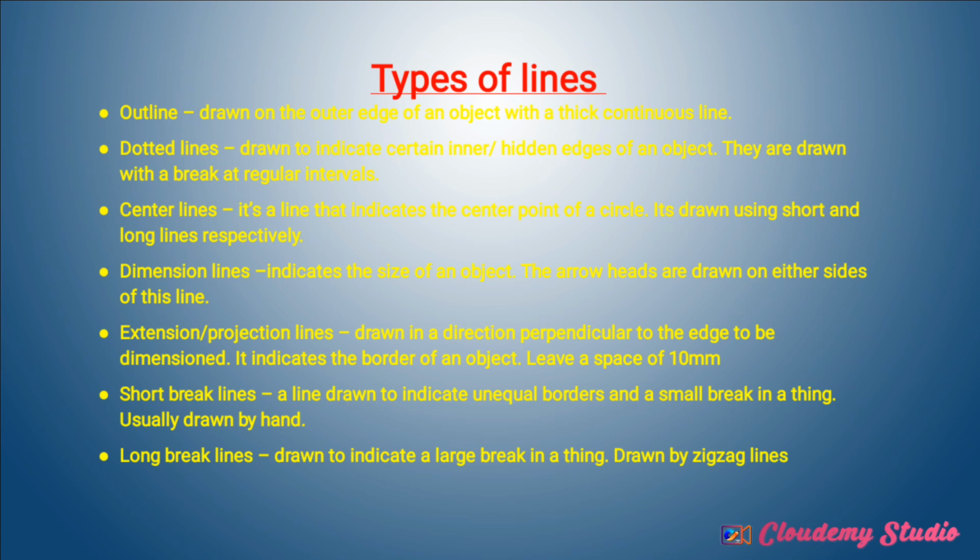So with that, it will enable you to avoid the confusion of knowing the exact length of the object and also to avoid overlapping of lines. Then you have the long break lines and short break lines. The long break lines, I said, are used to indicate a large break in a thing, and they are drawn by zigzag lines. Then the short break lines are used for a small break in a thing, and are usually drawn by hand.